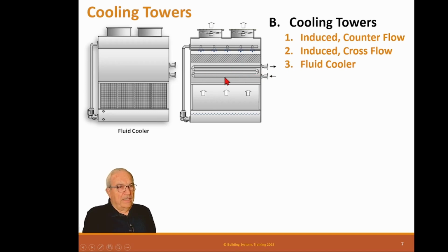This heat exchanger has another water stream going through it, and these are used to serve things like water-cooled package equipment, hydronic heat pumps, or a process. I've had these where we've cooled laser beams and stuff like that, but you don't want this water exposed to the cooling tower water, because this water is dirty. It's hard to keep clean. It has a lot of issues, and you don't want to clog any small heat exchangers, so they use this separation of the two.